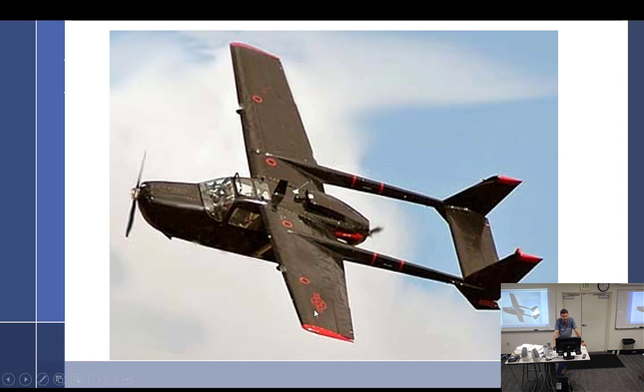What would happen is in a regular side-by-side twin, you bring the power on. If one engine isn't producing thrust, you're going to know it right away. You're going this way really fast. Whoa, something's wrong. In the Skymaster, you bring both engines up. You can see the front one. You can't really see or hear the rear one. I mean, you can hear it if the front one's off. You go, oh, I definitely got it. But otherwise, you don't notice.